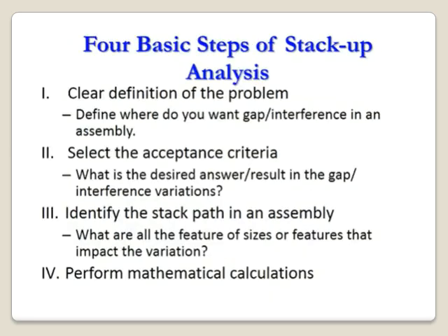Four basic steps of a tolerance stack-up analysis. First, we should have a clear definition of the problem. Define where you want the gap or interference in an assembly. We should know where we are trying to figure out a gap.